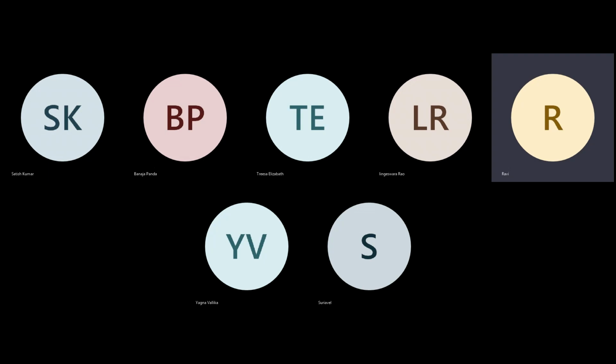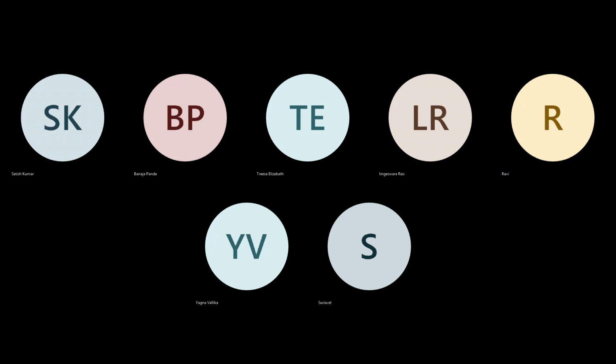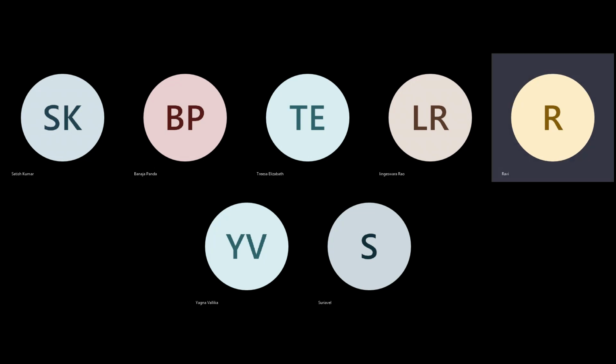So in that particular cell domain, like a 7 cross 7 matrix, if there is more than 95%, then it's a violation there, and it will try to de-violate. If you have put a density screen, for example 50% only, then it is going to check against that criteria: at 50% density, I'm not supposed to place like this.